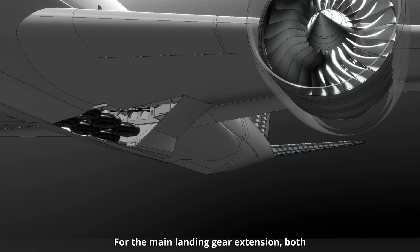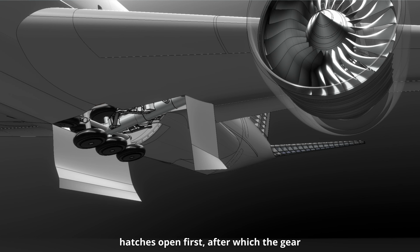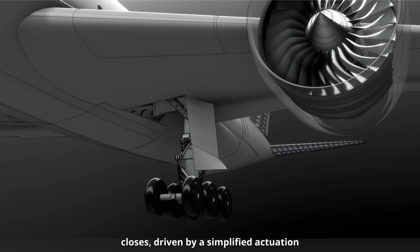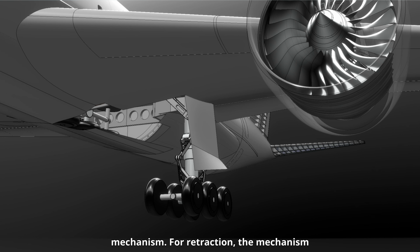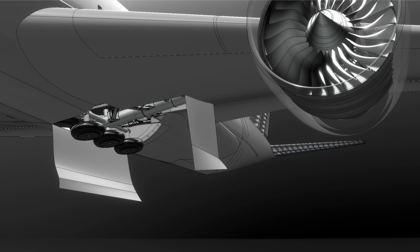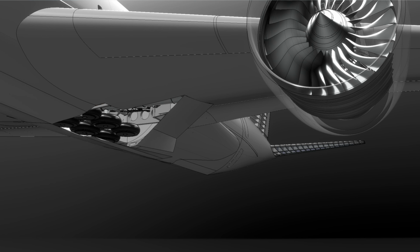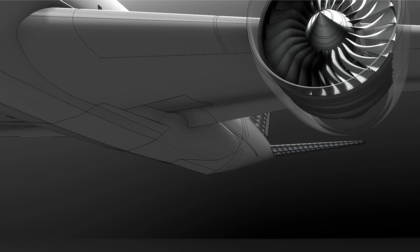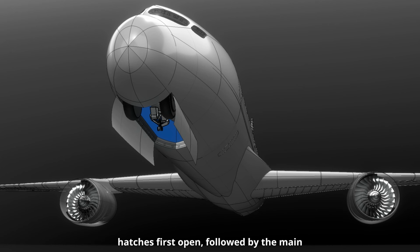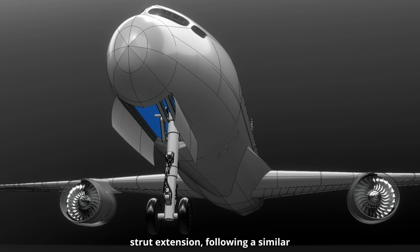For the main landing gear extension, both hatches open first, after which the gear rotates out through approximately 90 degrees before the inboard door then closes, driven by a simplified actuation mechanism. For retraction, the mechanism is the exact same but in reverse. Similarly, the nose landing gear's hatches first open, followed by the main strut extension, following a similar simplified actuation mechanism.